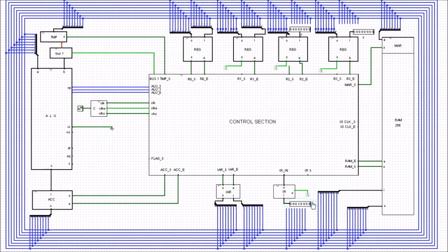And then what we want to do is store the value of this register here. So this is going to be register 2, so that's 1, 2. And we want to store this value in this register into the memory address pointed to by this register, which is register 3. So we're going to put in our register 3 there. So this is just our RA for these 2 bits and RB for these 2 bits.